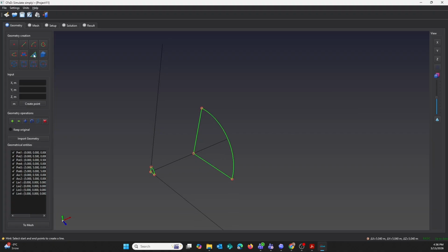After using the line tool, we can use the create surface tool and select each line to create a surface for both arcs. Now we will use the pull function. We can do so by pressing the pull function in the Boolean operations, the little rectangle with the arrow, and selecting the smaller arc surface. The yellow arrow indicates the direction where the pull will be.